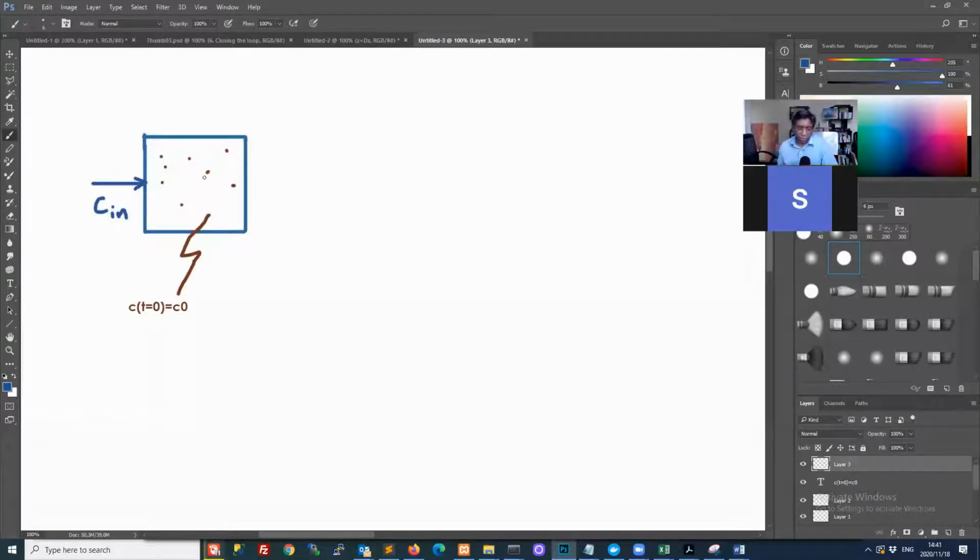So you've got some initial concentration in here, and you are feeding a stream in, and there's some other concentration in the stream. So you might have initially 5 moles per cubic meter in here, and you are feeding 15 moles per cubic meter in here. So those two are not the same, and it's confusing because in many textbooks they use C0 and C in interchangeably. So don't be surprised if you see that. Just carefully work out for the problem you are looking at, what do they mean by that C0? Do they actually mean C in? And once that's established, the rest will follow.